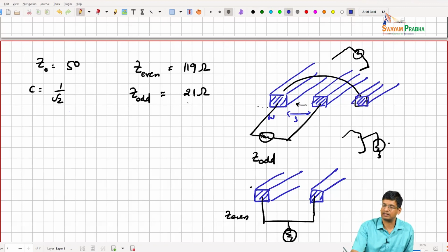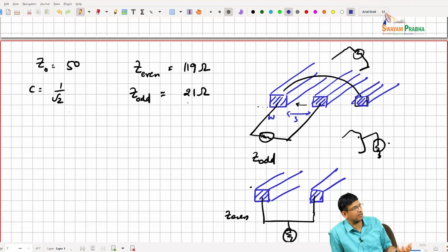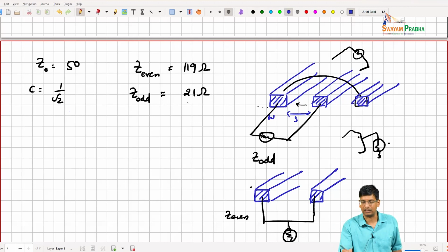So now basically this port is connected to this. Because we are integrated, we can play tricks like this very easily, right? We can put a via structure that connects these two, and now this line is coupled very strongly with both the metal traces on the left and the right in order to give you a higher C, right?